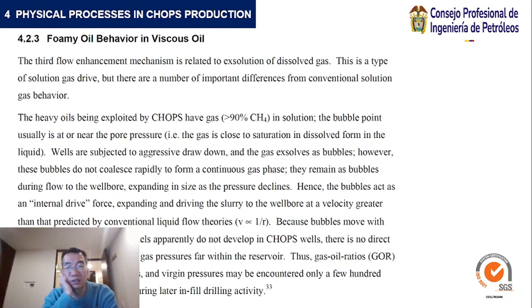Hence, the bubbles act as an internal drive force, expanding and driving the slurry to the wellbore at a velocity greater than that predicted by conventional liquid flow, because bubbles move with the fluid and discrete gas channels apparently do not develop in CHOPS wells.